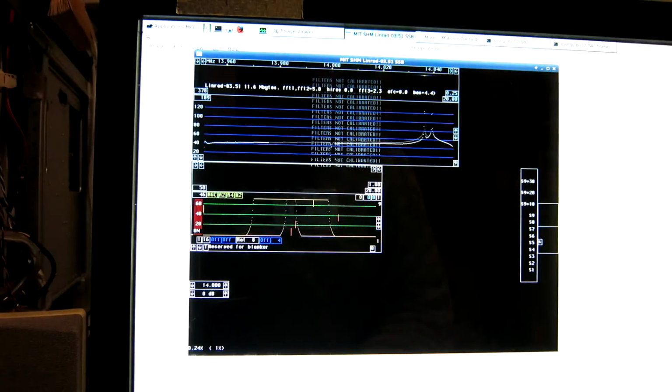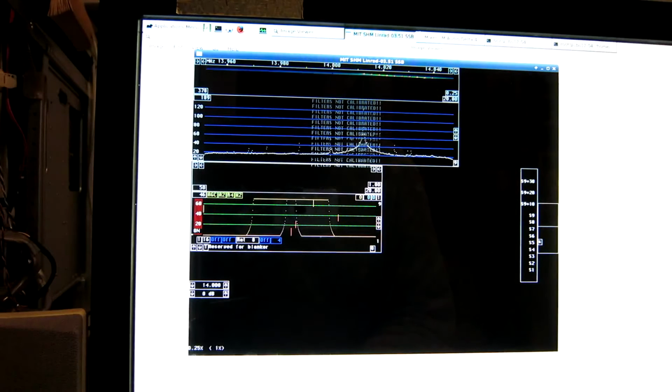So you can see the keying clicks from stepping the frequency is far stronger than the mirror image, which is at a little bit above 40, while the signal is a little bit above 120. That's about 80 decibels. That's about what you get doing it this standard way.